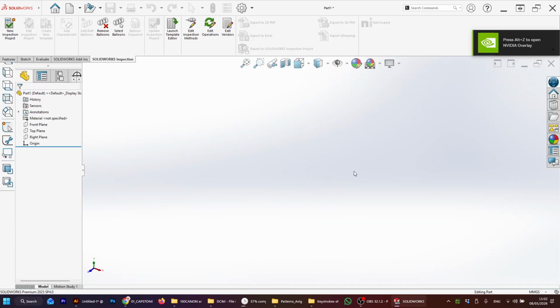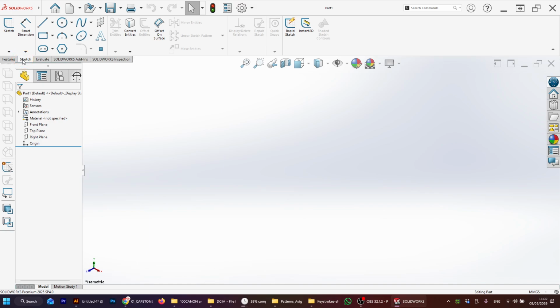Now, if you want to check or select, sometimes the first time you open the software, it's going to ask you to choose if you want IPS, inch, this and that. You need to choose millimeter, gram, second. If you see millimeter, gram, second, leave it on that, with ISO or ANSI, something like that, then be sure. This way you're going to work in millimeters, and then you can switch to centimeters, but you're not going to have to bounce between inches and millimeters. If you prefer inches, go for it. You will have to divide or multiply by 2.54 every time.